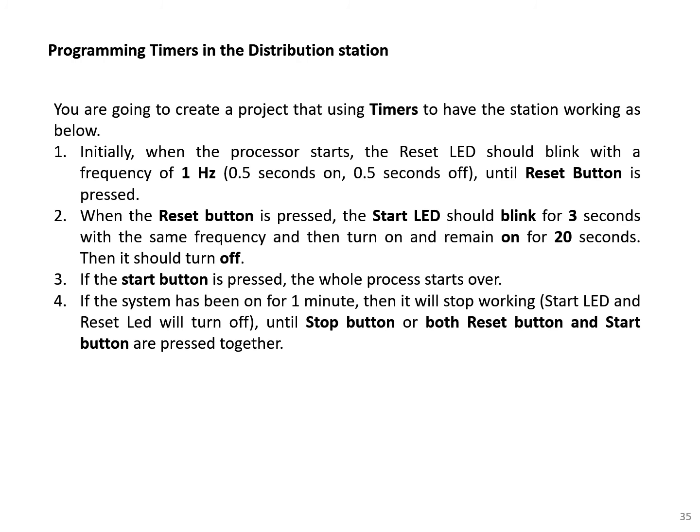When the reset button is pressed, the start LED should blink for 3 seconds with the same frequency and then turn on and remain on for 20 seconds. Then it should turn off. If the start button is pressed, the whole process starts over. If the system has been on for 1 minute, then it will stop working.